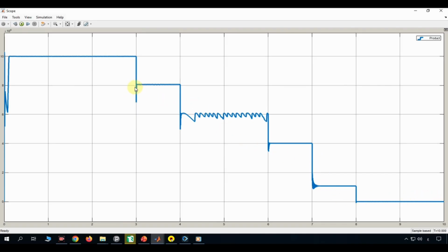During testing, we observed oscillations immediately after each irradiance change. This ringing occurs because the inductor and the input capacitor form a lightly damped resonant circuit. A sudden change in the reference voltage excites this resonance. The solution is to limit the rate of change of the reference voltage and ensure that the controller bandwidth remains well below the resonant frequency.